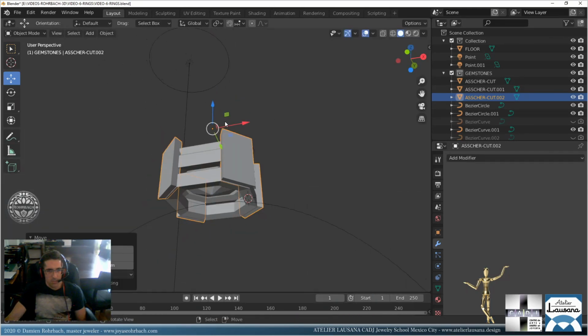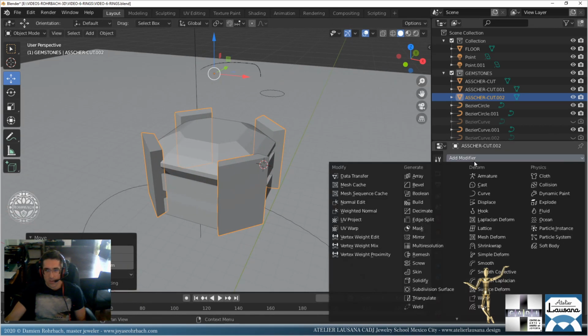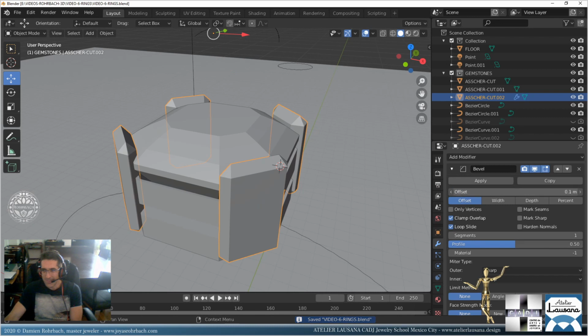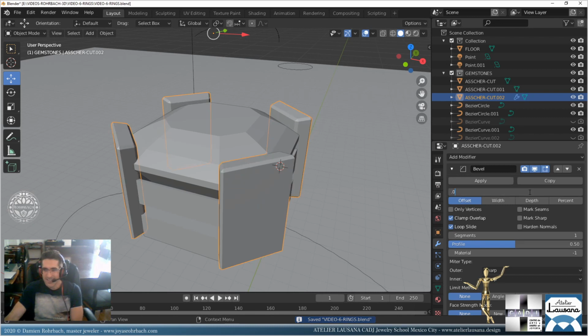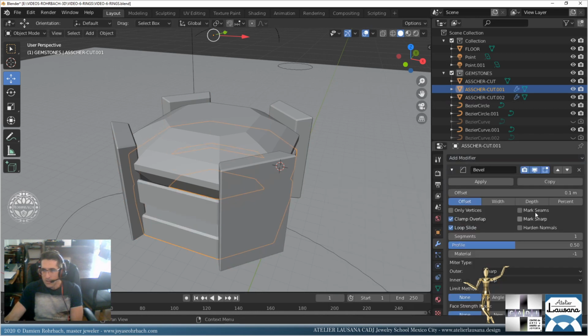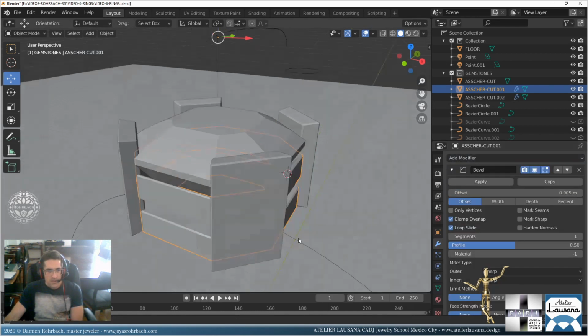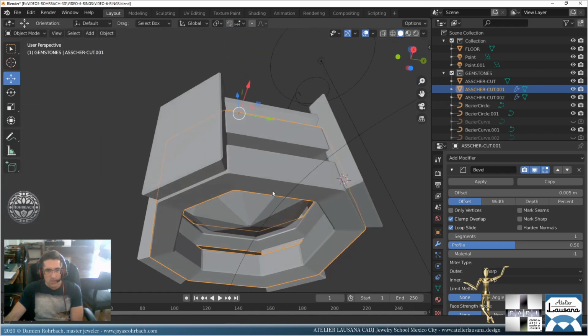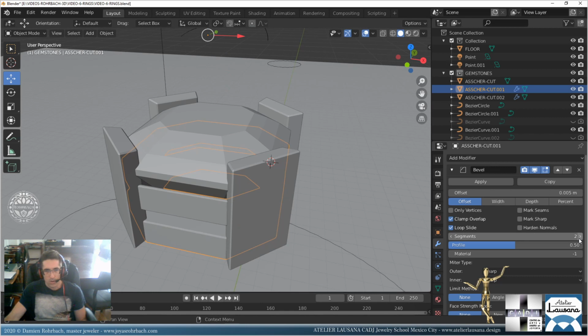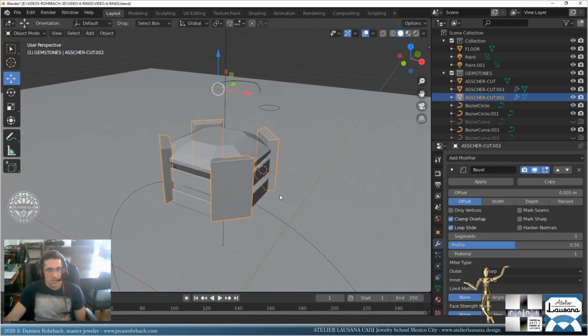Let's move it up a bit, just like that. Okay, so this we can bevel. Just this time I'm going to make it way smaller, and beware of my numbers. Oh, 5, that's nice. For this also, bevel 0.05, something very small. That looks better. Beveling things look definitely better. You can put more levels. Let's put 3 levels, I guess.